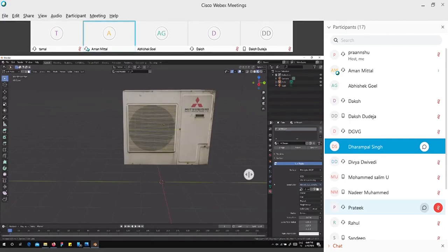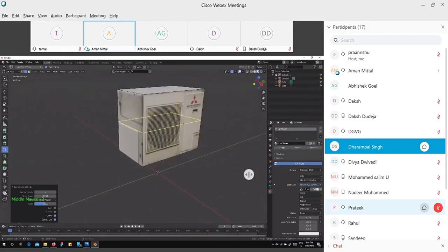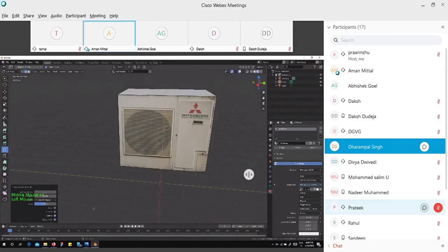Okay. I've selected these also. And when you have clicked one edge loop here, just open this menu, and if this option Correct UV is not checked, please check it. Otherwise, it will be messy. I will show you how it will be messy. I uncheck this button and move this, and the whole texture moves with it. So we don't need that. We will add this edge loop, correct the UV, and now if we move it, it is fine.